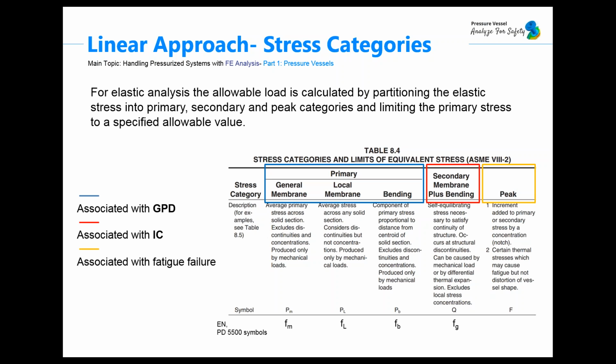So basically, primary stresses are the most critical stresses for the design, meaning that if they exceed yield stress, they will lead to failure without any doubts. They are caused by mechanical loads, and they are needed for fulfilling the laws of equilibrium, of moment, of forces and pressures. And primary general stresses are characterized by not being self-limiting,